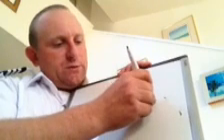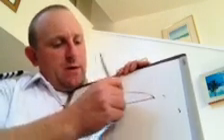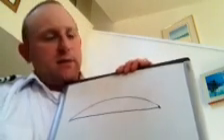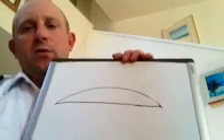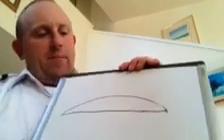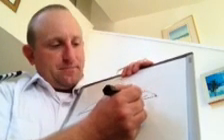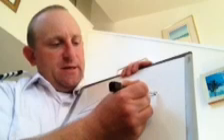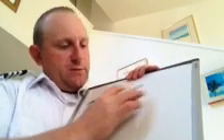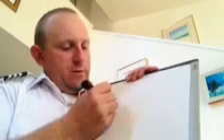The other flap that I want to cover is what's called our Fowler flap. Our Fowler flap is slotted like a slotted flap, but it also works by increasing the surface area of our wing. So we're going to get the most lift out of a Fowler type flap. The flap is kind of on tracks. I'm going to redraw this so I get a little more room here.